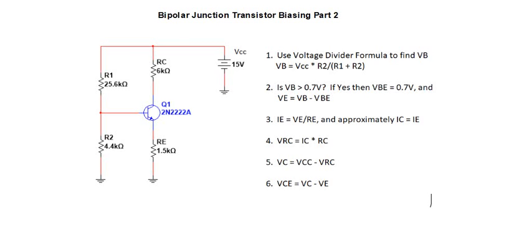And just to refresh that a little bit, before I go to the next page, I've listed out the steps here that we go through after we find that load line to find all the other voltages and currents in the circuit. We've got 3 currents, and I'm really talking about the transistor currents. I'm not that worried about the current through R1 and R2, but I'm talking about IC, IE, and IB.